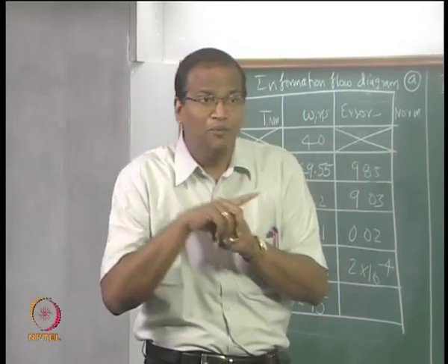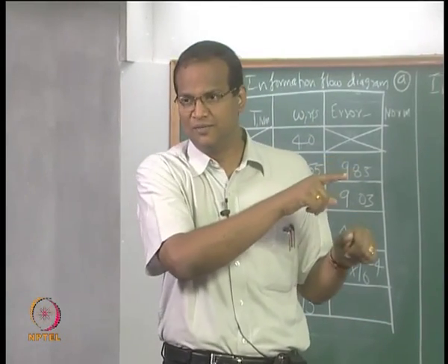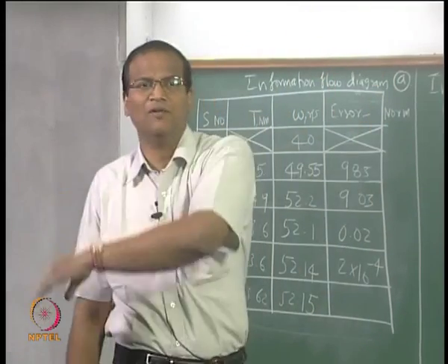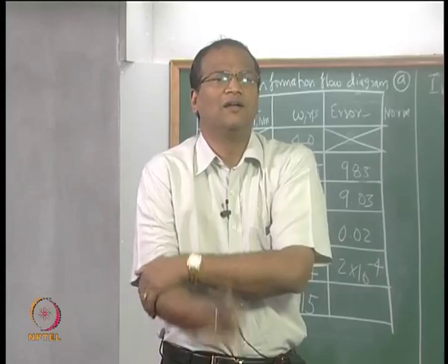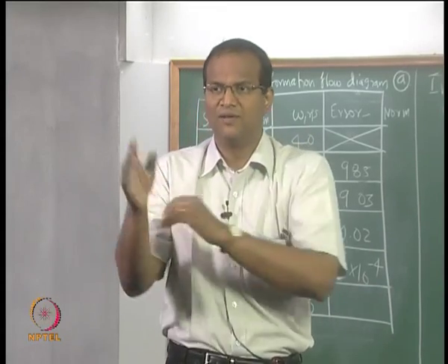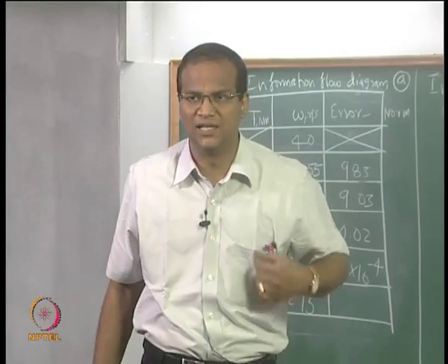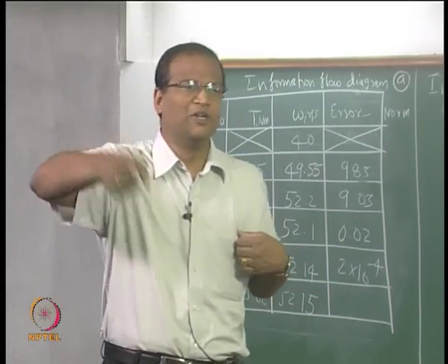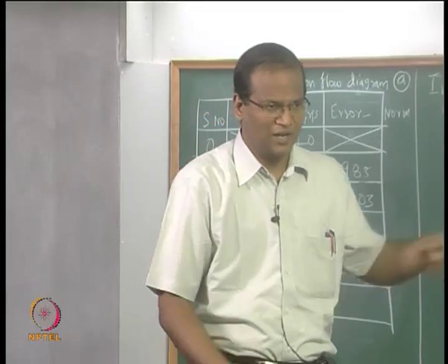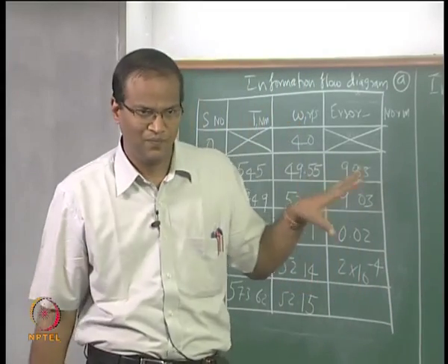I did not put the algorithm in Microsoft Excel and solve; I just took some arbitrary values of the parameters, used the fan curve and the duct, and saw where these two were intersecting. But Abhishek told me there is a way of doing it: we can put it into a recursive relation and actually show it on Microsoft Excel, okay.